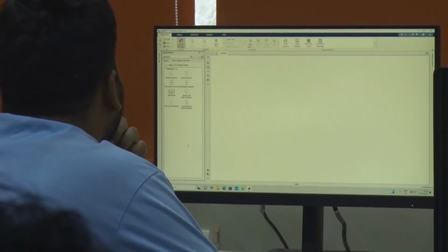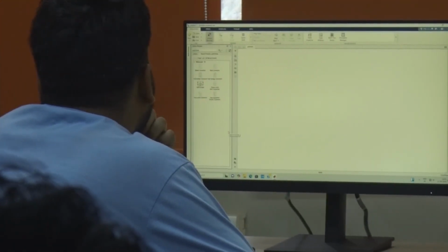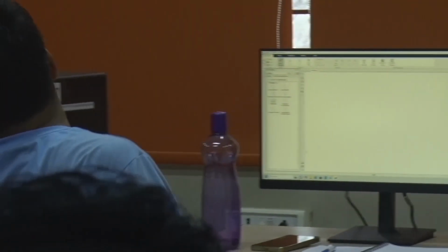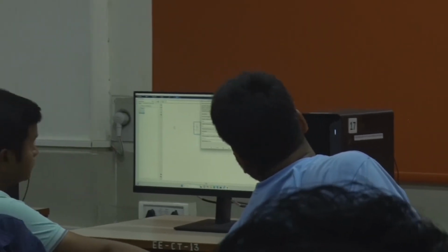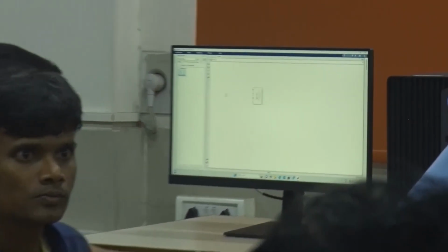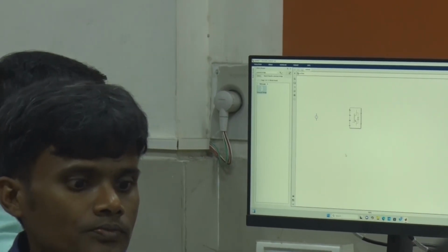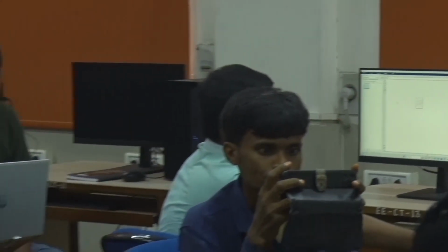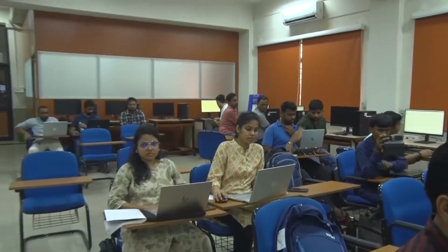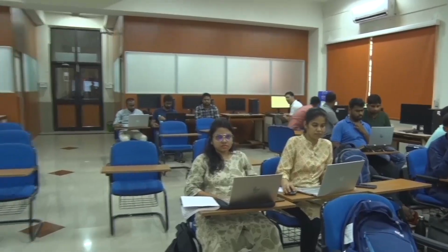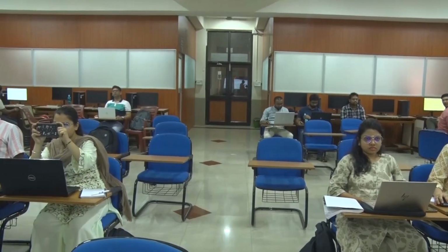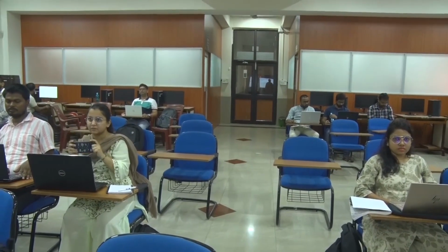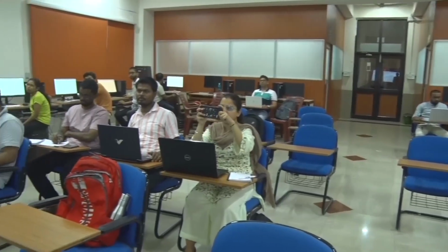So basically, we use the IL current, we control this current, right? So we need a current measurement from here. We have to regulate this voltage, so we need a voltage measurement here. Finally, what is the power delivered at the output? It is this voltage multiplied by this output current. So therefore, we need a current measurement here. At least this much we need. And this is how your system will work. Basic system. Okay.